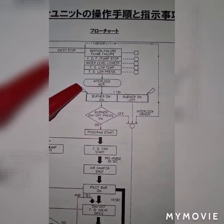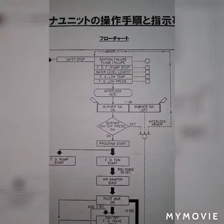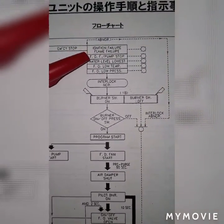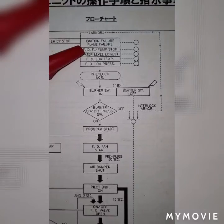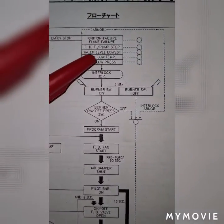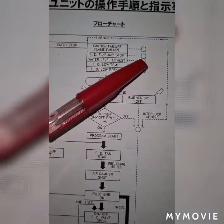As you can see here, this safety alarm, trips, and abnormal conditions of the boiler state the alarm for ignition flame failure, the forced draft fan and pump stop alarm, the water level lowest alarm, the fuel oil low temperature alarm, and the fuel oil low pressure alarm.